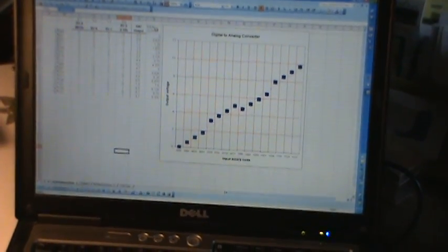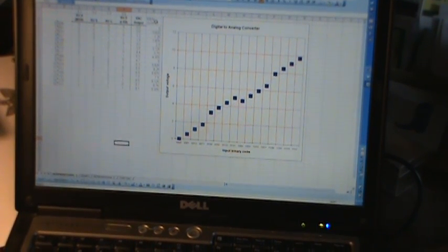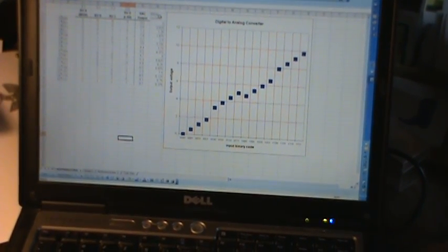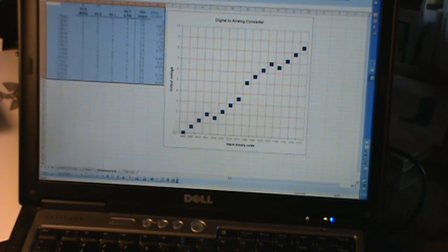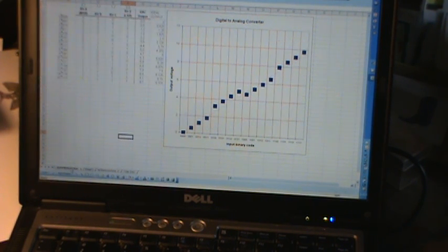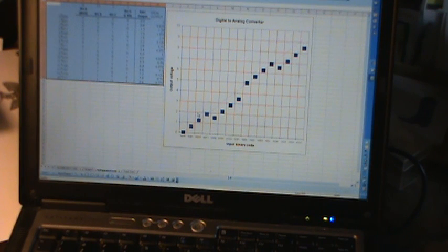What we're seeing here, it shifts up, shifts down, shifts up. If we kept going, it would shift down again. Now the converse of this, because we recognize it's happening with the second most significant bit. Here's another case where instead of being too large, like in the case we saw here, our 4-bit, or four times as big as the LSB bit, or B bit, here it's smaller, so it shifts down, then up, then down, and so you can see more strongly the non-monotonicity when this thing kicks in.